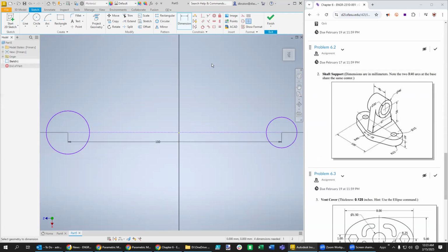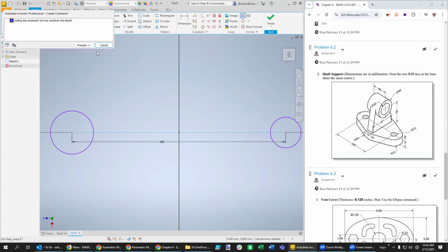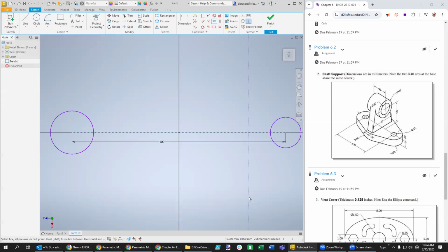And hopefully we could use the coincident tool to find the midpoint of this line. I'm not seeing it. Oh, there it is right there. We want to make this midpoint right there. And it looks like it probably already has the horizontal constraint that says that one's vertical. Let's make that line though horizontal. Looks like it already knew that as well.